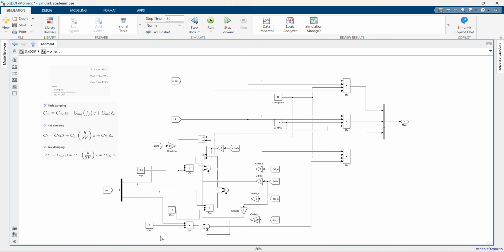Sometimes your Euler angles six-DOF block may be considering a different sign convention in the background. So the only way you can fix that is you look at your plots, you play with this, you run the analysis, you look at the analysis. If there is a sign difference, then you know you come here and you fix this. Also, CNR over here, if you notice yaw damping, that has CNR, and that is responsible for helping in damping the yaw behavior.